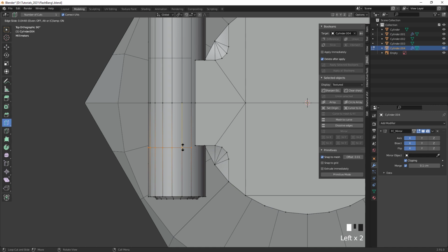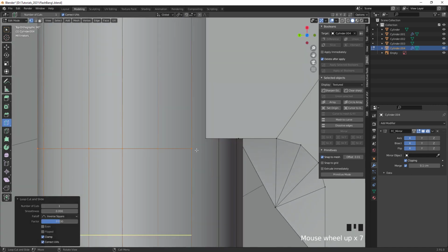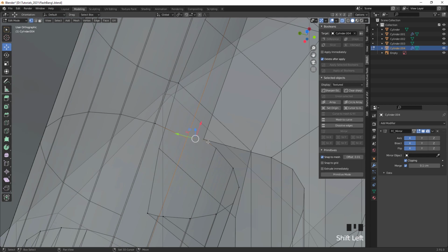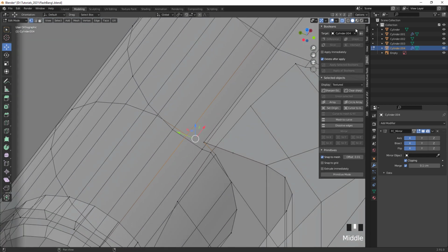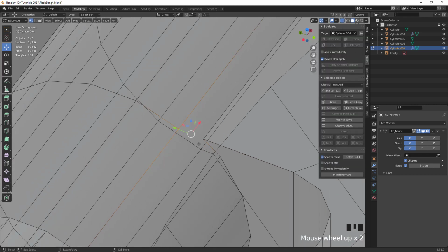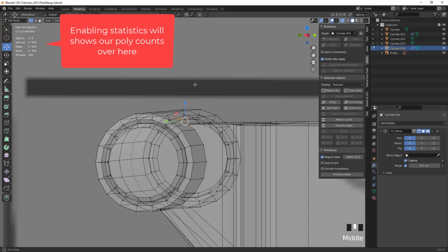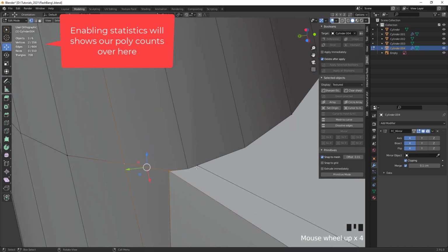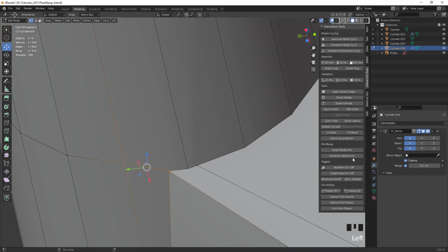And now with the edge loop cut, let's have another edge loop here, and then we can connect that here with that element. So sometimes it's hard to see what we have selected, and I want to enable statistics, and now you can see that we have 2 vertex points selected here. So we should actually always have the selection on. And then I'm just gonna also join it here at the bottom. So both at the top and at the bottom we have some connections here.